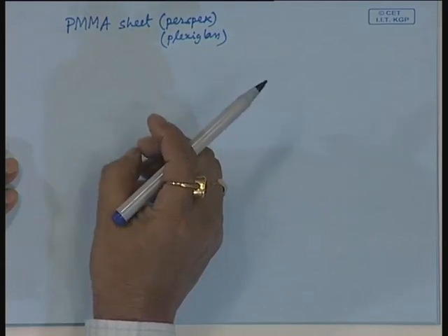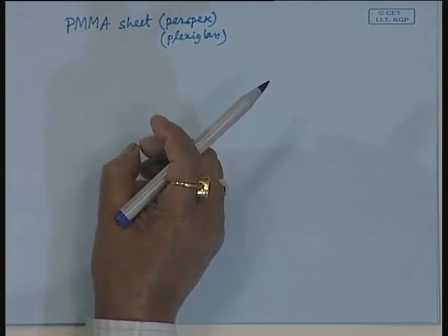Then you can have a sheet mold, sheet die. It may be a 1 centimeter thick sheet, 6 millimeter, 5 millimeter, or 20 millimeter thick sheet, like that. That means a rectangular mold having a rectangular cavity inside. Now, this pre-polymer is poured into that cavity, and the rest of the polymerization, say up to 70% conversion, is carried out there.